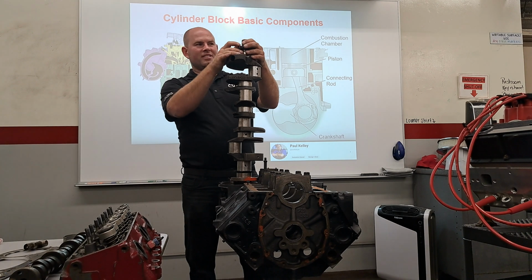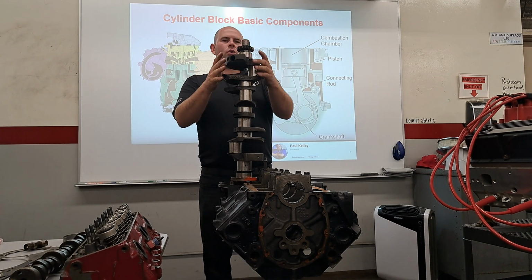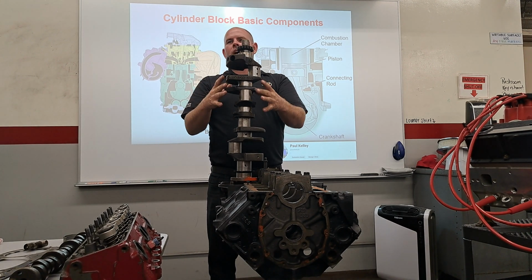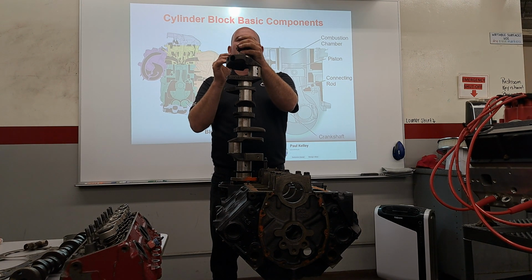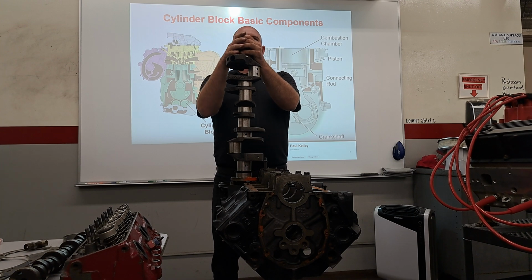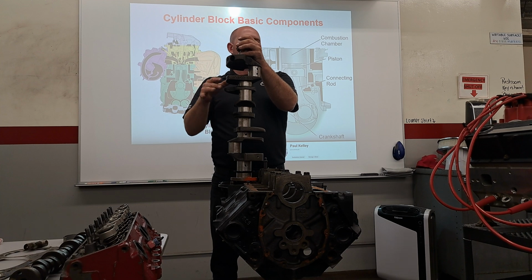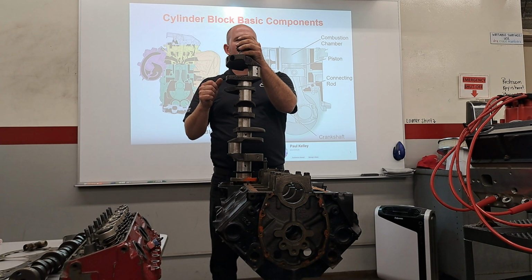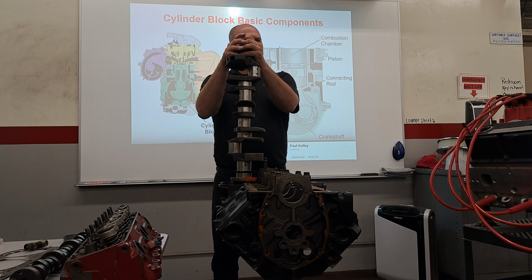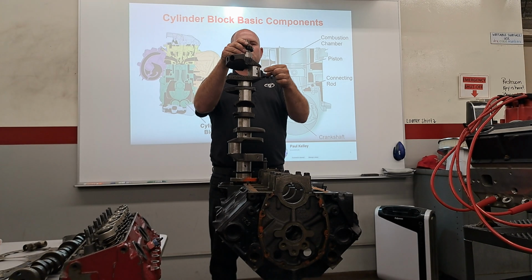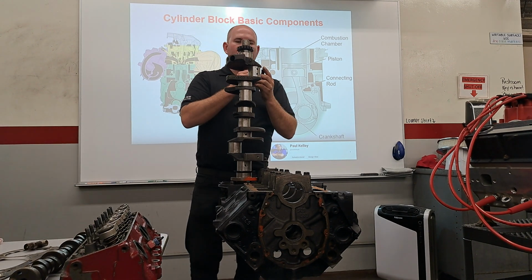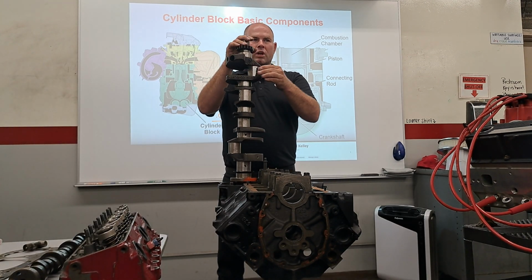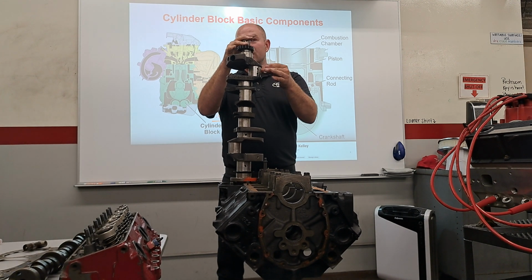So you guys kind of understand the difference between mains and rods? Now let me just give you a quick explanation. If you had an engine and it was knocking, it can be a little tough to tell sometimes if it's rods or mains. Mains tend to be a little more consistent, thumpy. Rods tend to be a little more clattery. But the thing to do, let's say this was cylinder number 1. If cylinder number 1 rod bearing has an issue, when you make a power stroke, you're going to get this, right? Because it's hitting, and let's say it's worn out, it's loose.